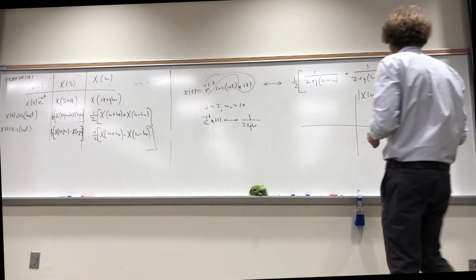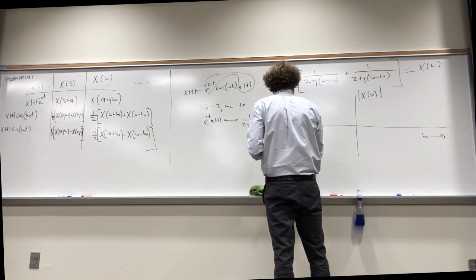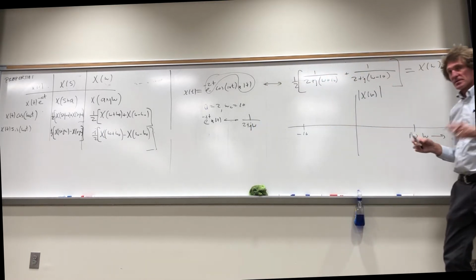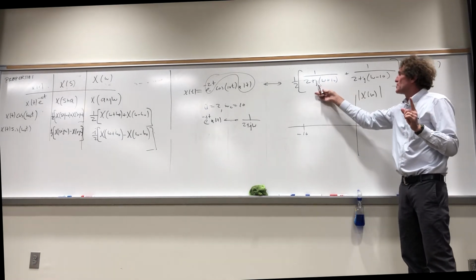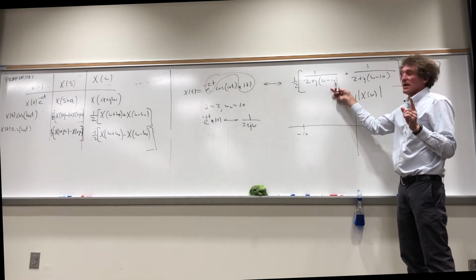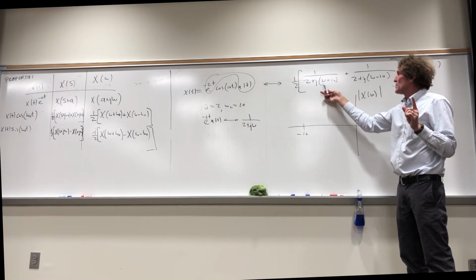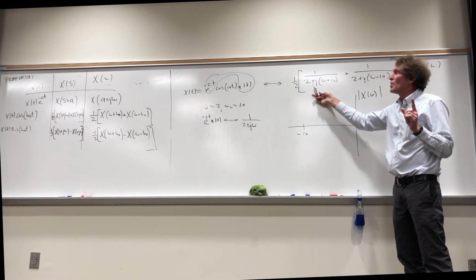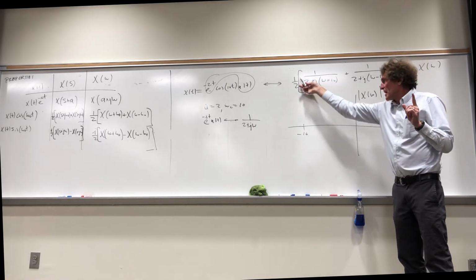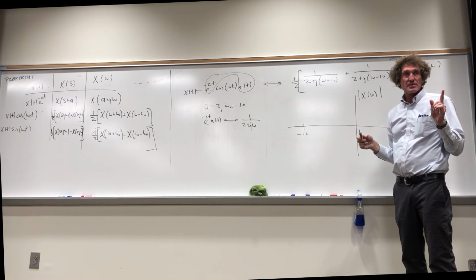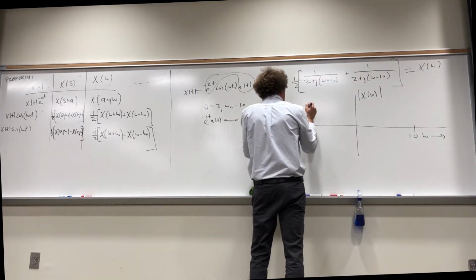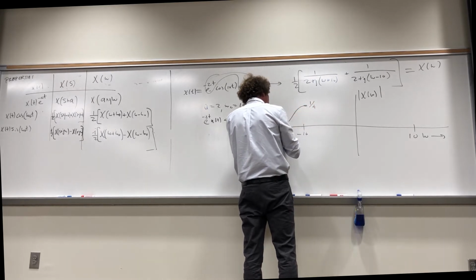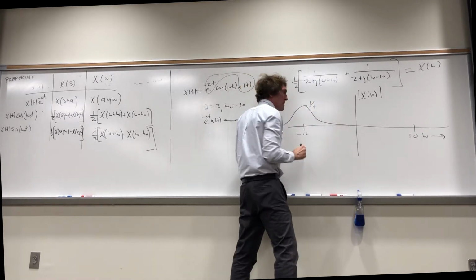The way you do this is you go down to minus 10 and plus 10. Those are the center points. Now, can you all see how this function 1/(2 plus j of omega plus 10) will have a maximum value when omega is minus 10? Minus 10 plus 10 is 0, so it's 1/2. Correct, class? Times the 1/2 is going to be 1/4. Agreed, class? So basically, this thing's going to have a height here of about 1/4, and it'll look like this. It'll be similar to a bell curve. All right?